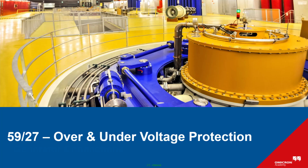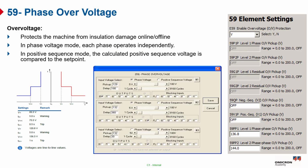the power generation systems. So as you can see, the overvoltage protection, known as 59 in the ANSI code, is designed to protect the generators and their connected equipment from excessive voltage conditions. It prevents insulation damage both when the machine is online or offline. In the phase voltage mode, each phase operates independently, while in the positive sequence mode, the relay compares the calculated positive sequence voltage to a defined set point.